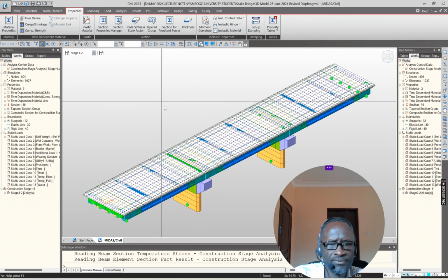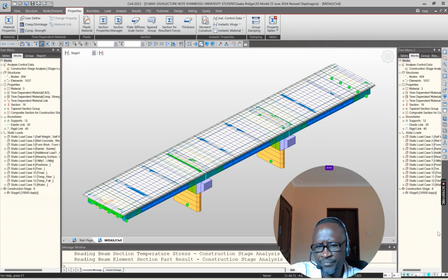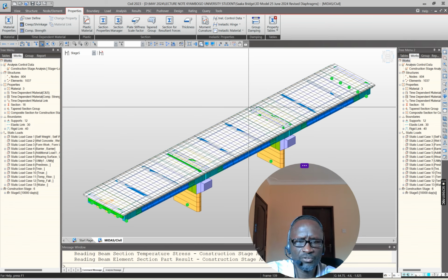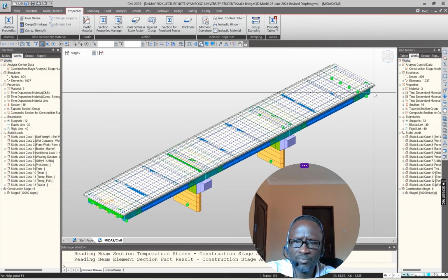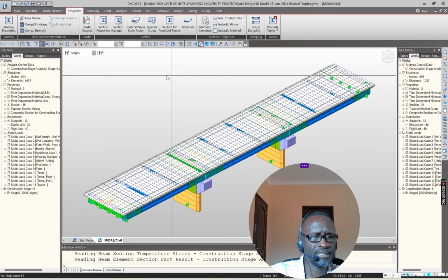After you have done all that, you come to the third and fourth stages. Once it is constructed and set, normally we take about one or two years. Once the concrete is set, you are able to put in the wearing course, what we call superimposed loading. You put the raised walkways, the wearing course, the services, and all other things. So basically that is that.